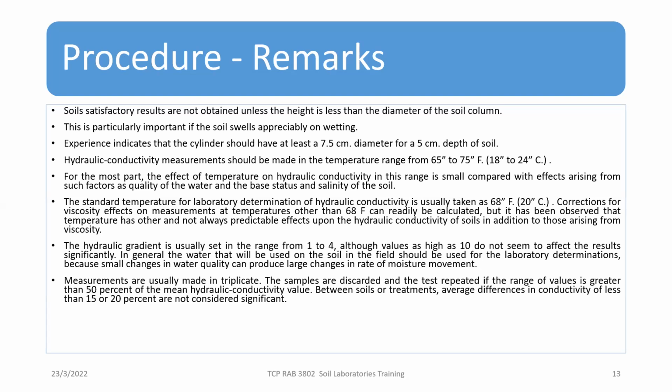The hydraulic conductivity, of course, because it deals with solutions, the quality of water has some pronounced effect, because it also will make some modification of the viscosity of the water. And of course, the salinity also has some effect on the hydraulic conductivity.